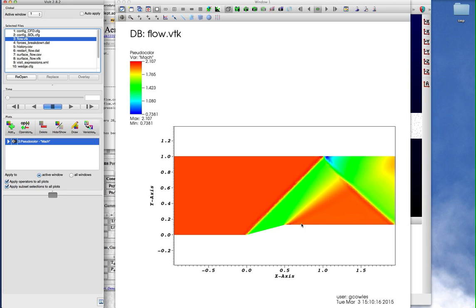So the flow has to turn. It's still supersonic, so it goes through an expansion right here. This is the Prandtl-Meyer fan right here. It's accelerating. If we go back to look at pressure in a second, we'll see that the pressure jumps across the shock, and then drops across this Prandtl-Meyer fan because there's an acceleration there involving turning this corner supersonically. A key thing is that the shock wave goes up, and something funny happens up here. And this is called a Mach reflection.